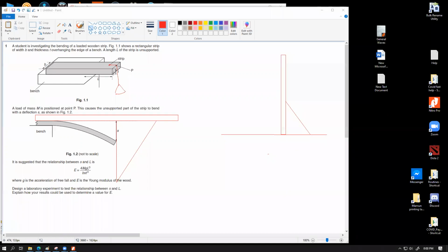It is very important that we mention the word identical, or made from the same material, because we are trying to measure the Young's modulus of the wooden plank. Unless you have identical pieces of wood, it would be pretty difficult to have a uniform value. You cannot use two different species of wood, which would have different grain density or other properties, so that you will have different values. Your graph would give you a kink or something like that. You wouldn't want that to happen. So we should use identical pieces, or if possible, the same piece of wood for the whole experiment.